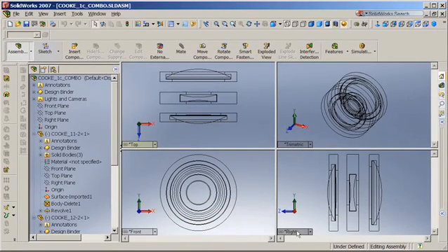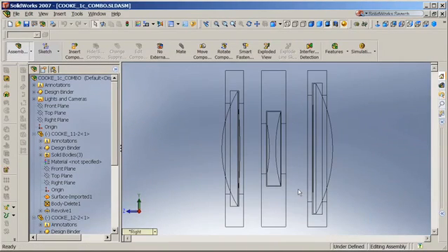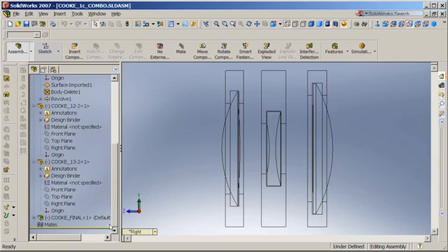Okay, so here's the file in SOLIDWORKS, and again, let's expand this view to get a better idea of what's happening. And what we have are our mounts, our retaining rings around our lenses. We also have our lenses. Now, as a general rule, you don't want to export these optical components from the CAD program as an IGES or a CAD format file, because your lens design program and the ASAP translation understands optical surfaces generally better than the CAD programs do, so there's going to be less approximation if you use the files directly from the lens program. I only needed these lenses so that I could build the mechanical structure.